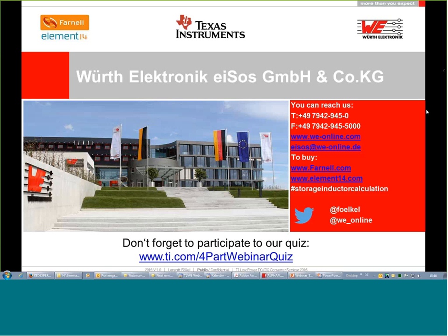So if you don't have enough space to fit a shielded version and the unshielded version has to be used, at least I would say try to fit the semi-shielded one, because it's better than the not shielded one at all. I would say you will improve by 20% the magnetic field kept inside, but not 80% like with the shielded version. In terms of EMI, a toroid is the best shielded inductance because its magnetic field cannot leak out. But who wants to use a toroid today? Think about your mobile phone.